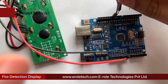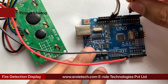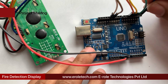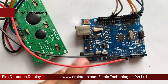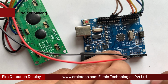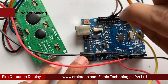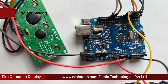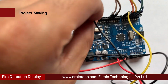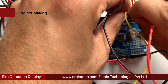Now connect white, brown, orange, yellow, green, and blue wires with pin number 12, 11, 5, 4, 3, and 2 of Arduino respectively. Now connect the red wire of sensor with the 5-volt pin, black wire with the ground pin, and yellow wire with pin number 7 of Arduino. Now connect the red wire of the buzzer with pin number 6, and black wire with the ground pin of Arduino.